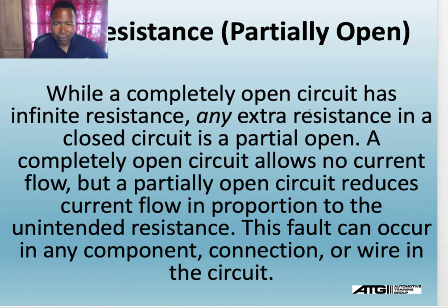A great example for that is a wire. I should have had a wire to show you. There's a wire right here. Can you see this wire? I don't know if you can see it, but it looks like it's connected. But internally, they have thousands of strands in there. If one strand is connected and everything else is disconnected, that's a partially open circuit.